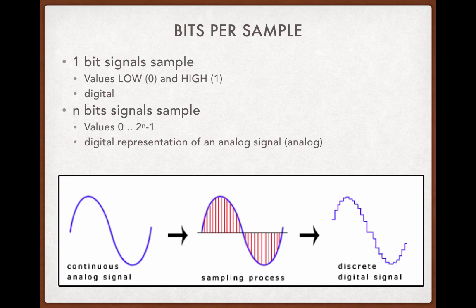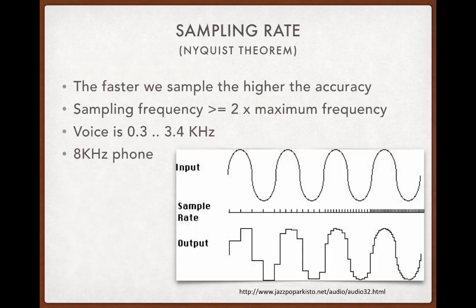We can see in this diagram we've got a continuous signal and we're taking samples from those red lines. Each sample is stored as a binary number representing that particular voltage level, and when we recreate the discrete digital signal back to its values, we only have those samples to go by. This means we end up with a somewhat step-like reconstruction of the original signal. This is termed quantization noise.